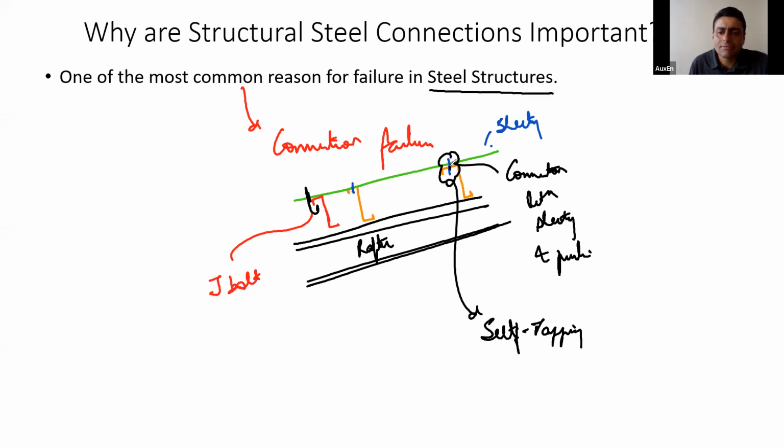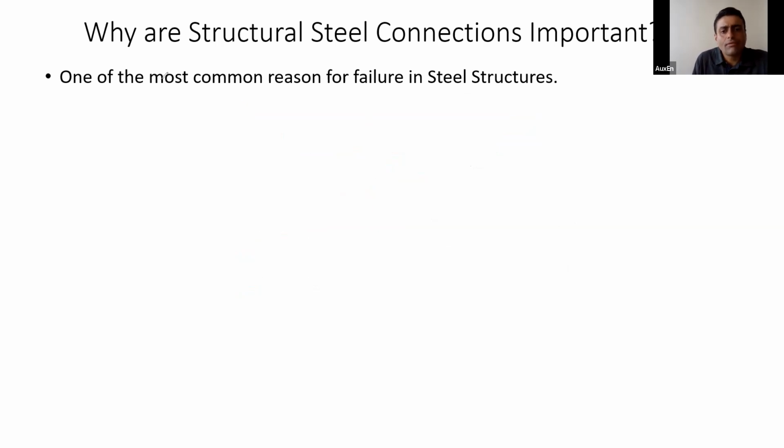They just slightly go inside, and there is a very poor arrangement that is made. These self-tapping screws can never withstand your wind. So this is a connection level failure.